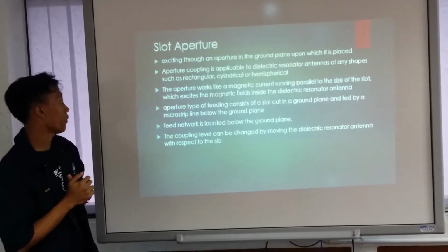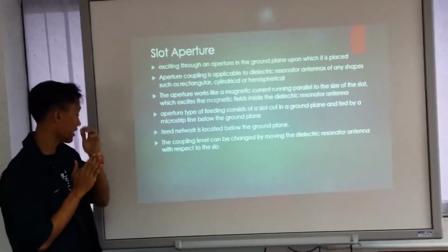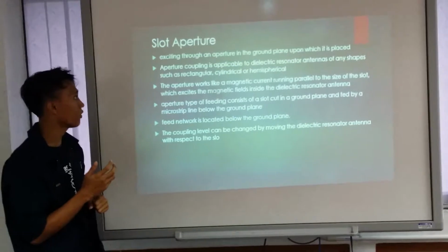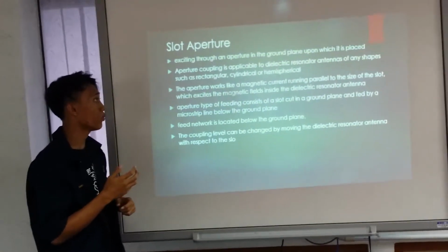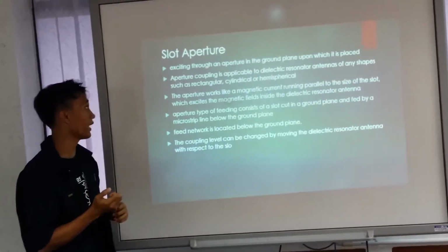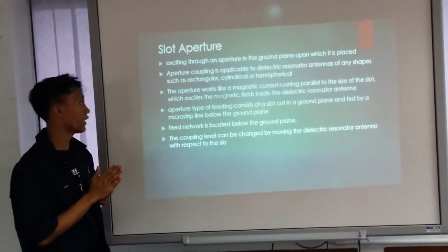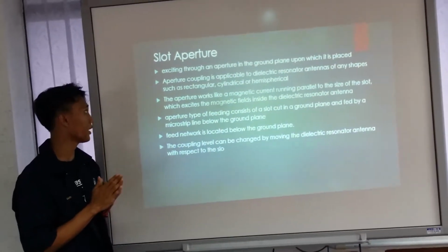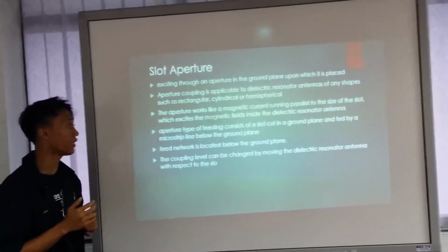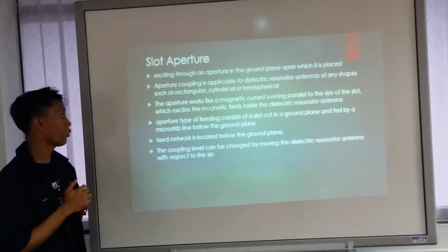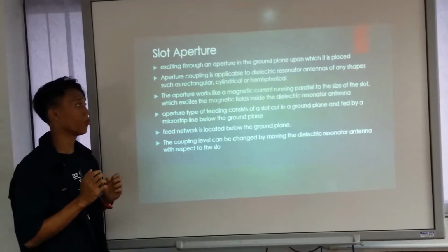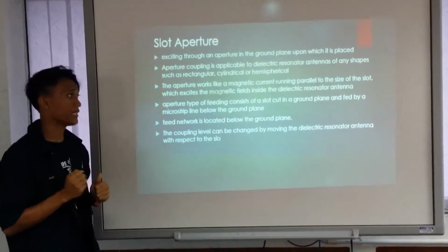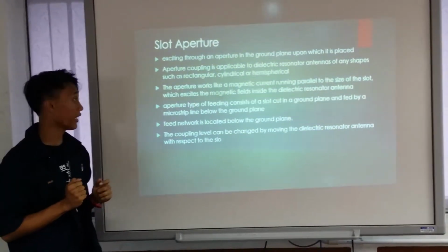And for the slot aperture, the slot is excited through an aperture in the ground plane upon which it is placed. Aperture coupling is applicable to the dielectric resonator antenna of any shape, such as rectangular, cylindrical, or hemispherical. The aperture works like a magnetic current running parallel to the side of the slot, which excites the magnetic field inside the dielectric resonator antenna.